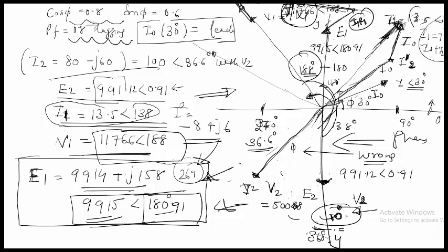So my V2, it will not make any difference in this case, because my V2, if I am drawing it, will be somewhere very close to this way, so that the angle in this case, this angle will be phi, which is the power factor angle. This is V2, and this is my E2 vector. If I am drawing as per scale, it could be larger or smaller. So this angle phi, which I found out, was 0.91 degrees, which is close to 1 degree. It's approximately, which can be said that my E2 and V2 will both lie on the y-axis.